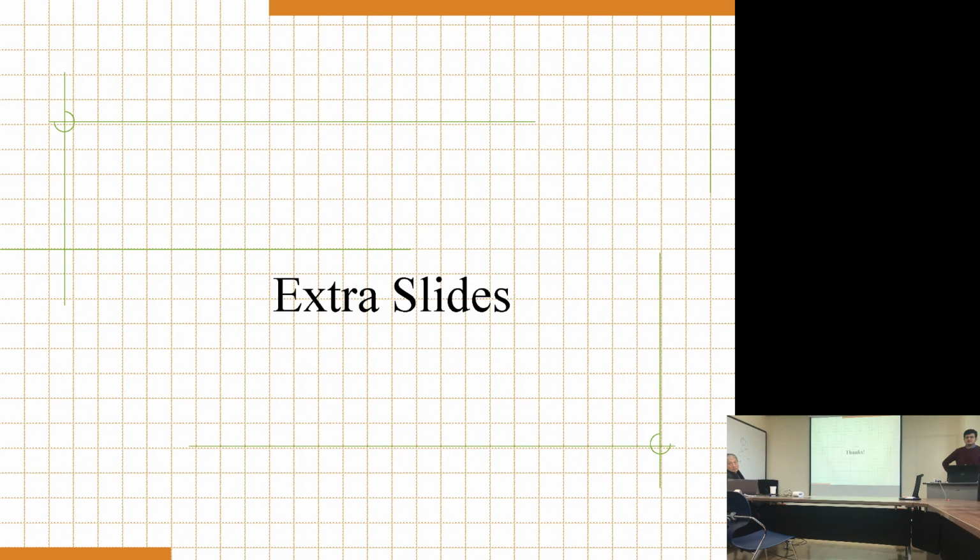Can you explain variational re-parametrization? Yes. I think variational re-parametrization is that, let's say, both our design and machine manufacturing system have one feature that is a hole, so the name is the same, but the diameter and length are changed in different ways and positioned using different reference systems. So the name is the same, but the input parameters which control the geometry are different.